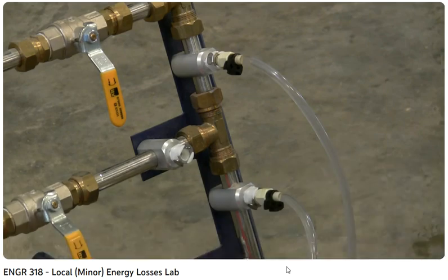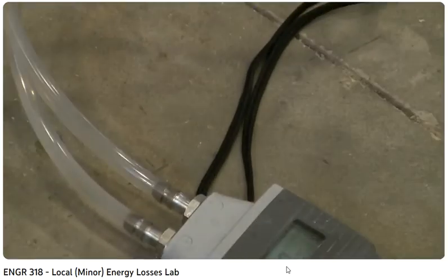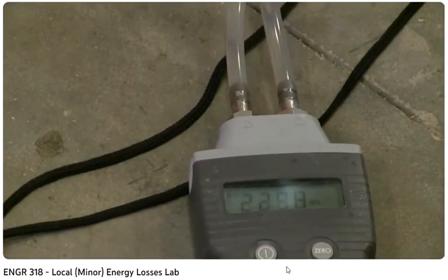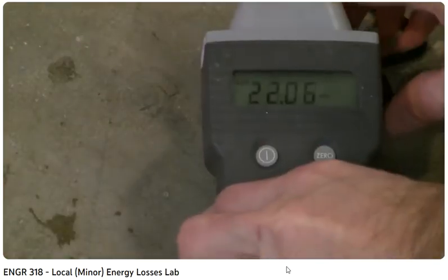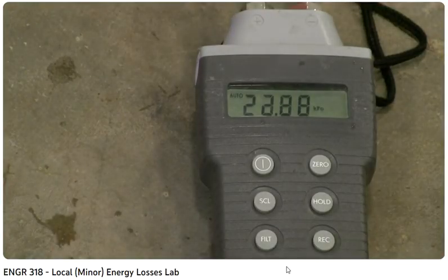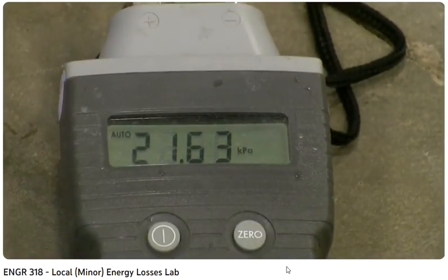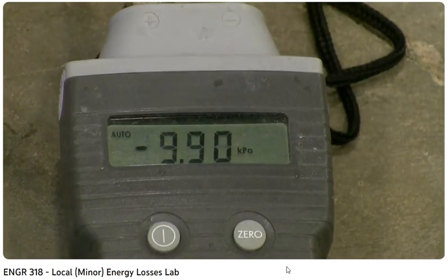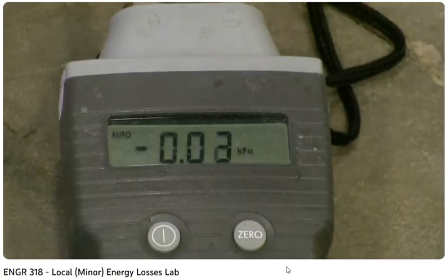Okay, so I'm turning on the pressure meter. Let me tip it up again. Okay, we are getting some pressure measurements. Let me close the valve so that there's no flow, and that should go back down to 0. Okay, so closing the valve. Not quite 0, let me 0 it. Okay, it's maintaining 0. I open the valve again to its original state.